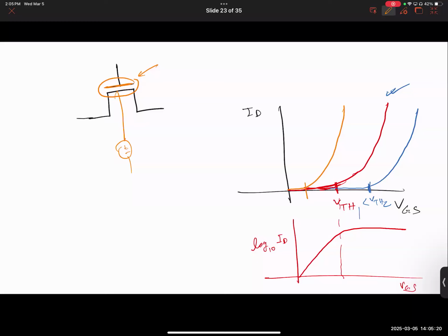If you somehow provide some fixed positive gate charge, it shifts the threshold voltage. And if positive charge shifts it one way, negative charge will definitely shift it the other way, as you can imagine. If positive charge increases the threshold voltage, negative charge will decrease it, and vice versa. Are we all good?